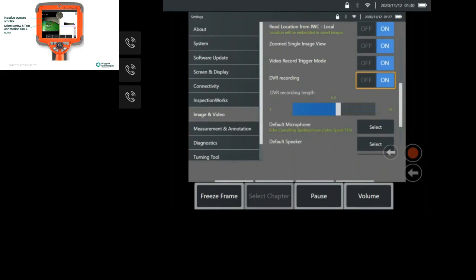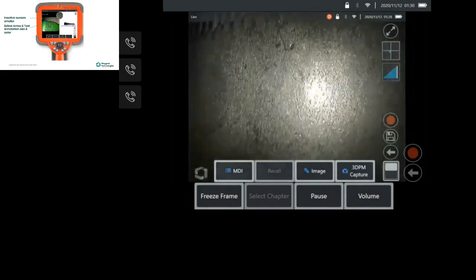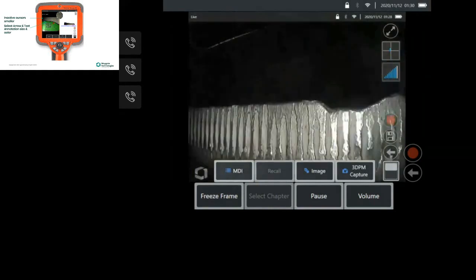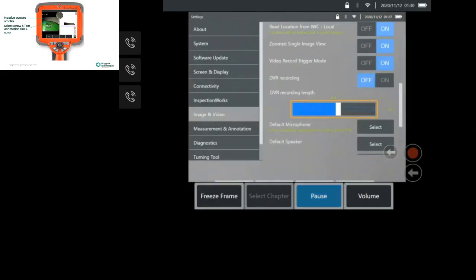If you recall, I was in my global menu initially, and towards the end of that sequence, I went back to a live image and was looking at a trailing edge of a turbine blade that had some erosion kind of damage in it, which I would expect to come up any moment now. So it's really handy to capture video to give somebody a perspective of what was going on in a scene and an asset when you recorded a still image that was measured upon.